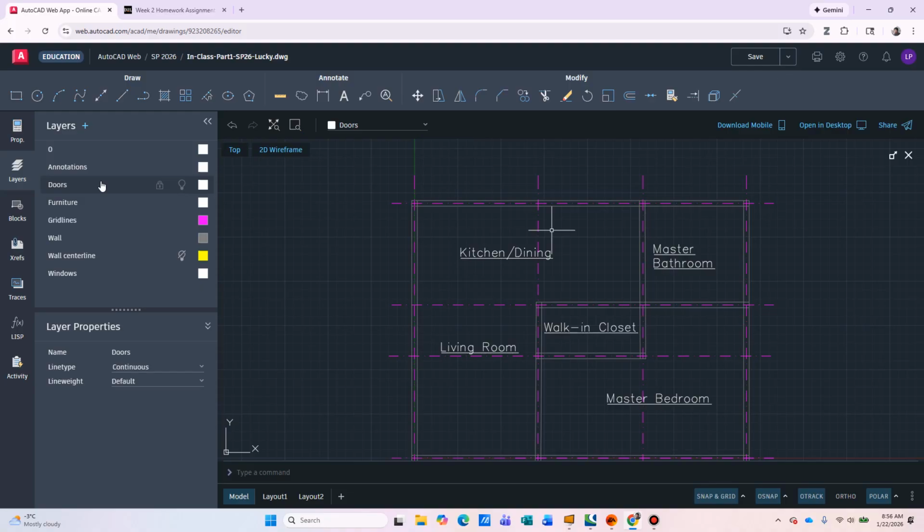And once you've loaded those block files inside your main project, you can reuse that block file however you want. You can multiply that, depending on how many rooms you got. And you don't have to manually draw it inside your main project. You can just click and drag those objects into your floor plan.